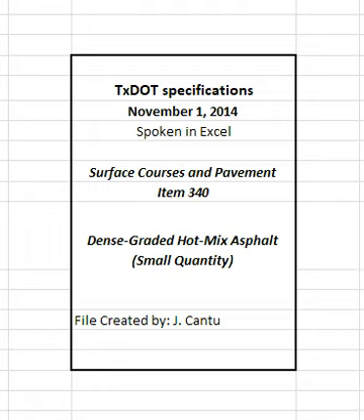Use fine aggregate, with the exception of field sand, from coarse aggregate sources that meet the requirements shown in Table 1 unless otherwise approved. Test the stockpile if 10% or more of the stockpile is retained on the number 4 sieve, and verify that it meets the requirements in Table 1 for crushed face count, TEX 460A, and flat and elongated particles, TEX 280F.